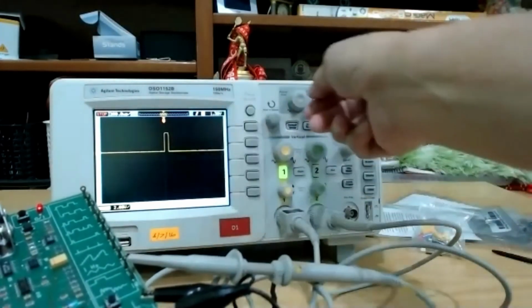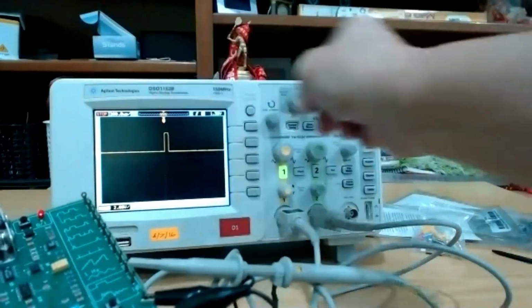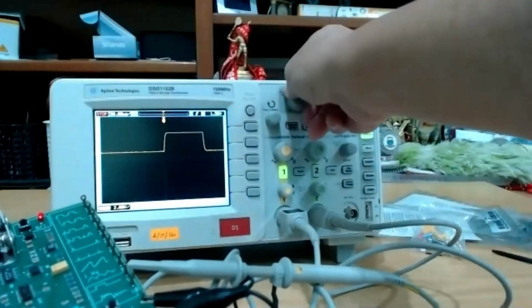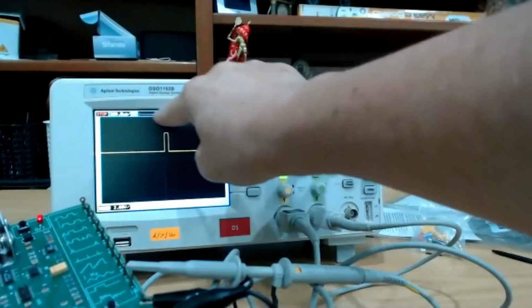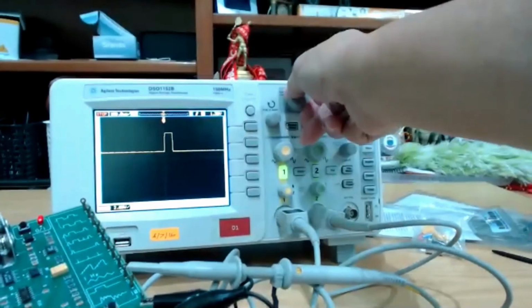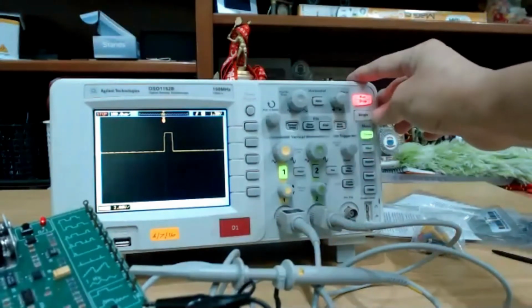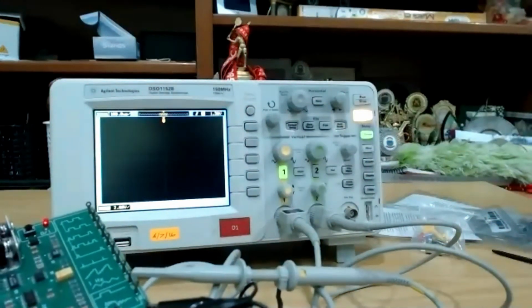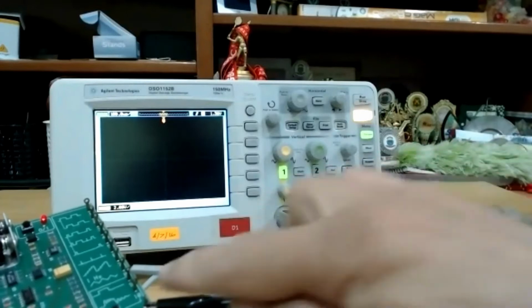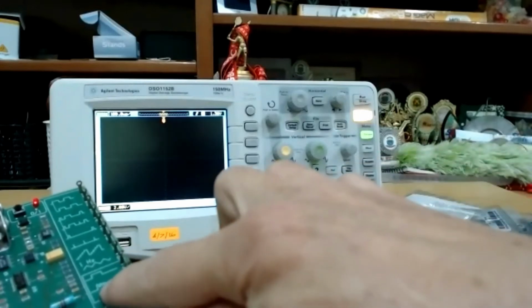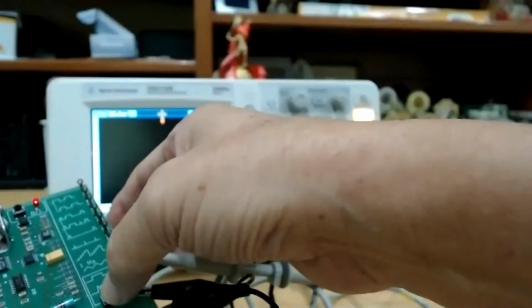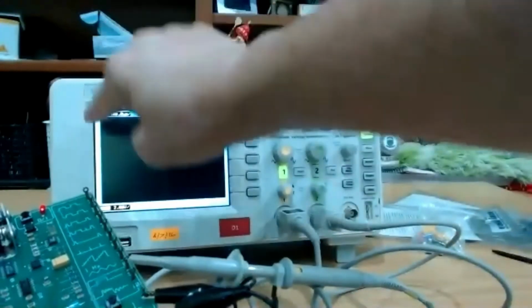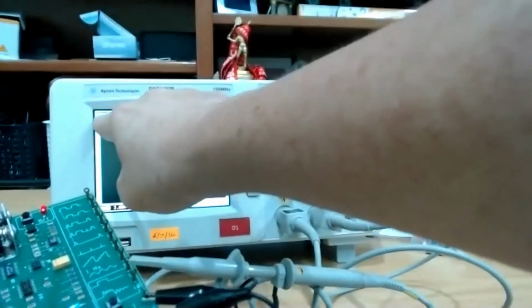Then for the signal in the digital storage scope, you can actually zoom in and zoom out and see for yourself under the zoom pattern here. If I do a single again, it will not show anything unless I press the button, that is, a trigger signal coming at this time. When I press, the scope is saying that it is waiting for a signal.